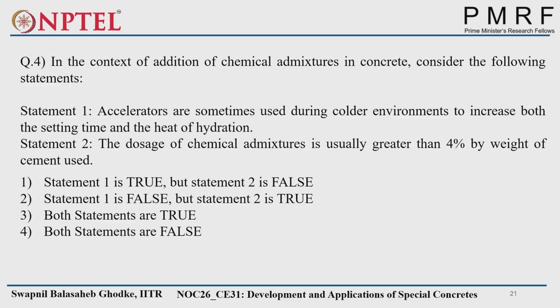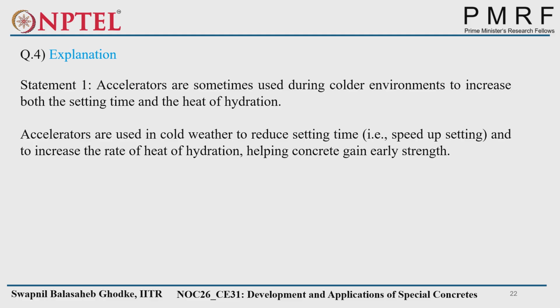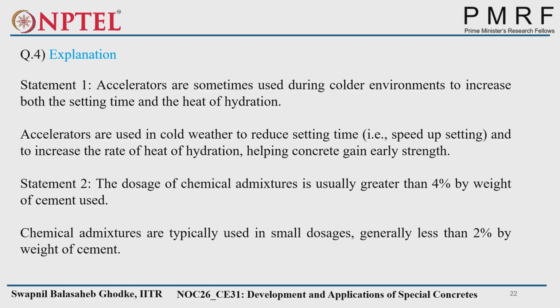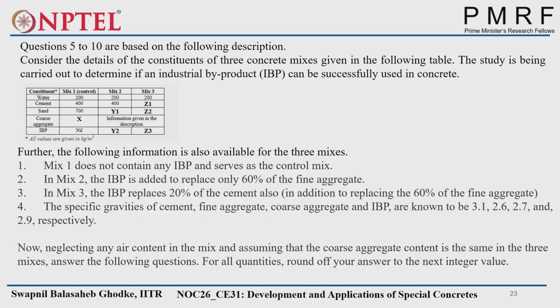Correct, both statements are false, because accelerators are used to reduce the setting time, not increase it. And the second one says up to 4%, but it is not. It is less than 2% of the weight of the cement, mainly. So both statements are false.